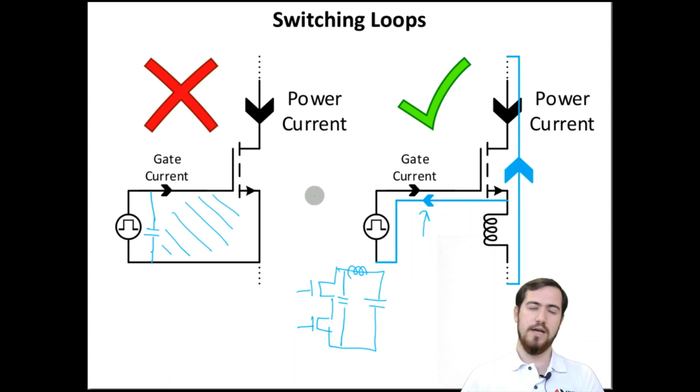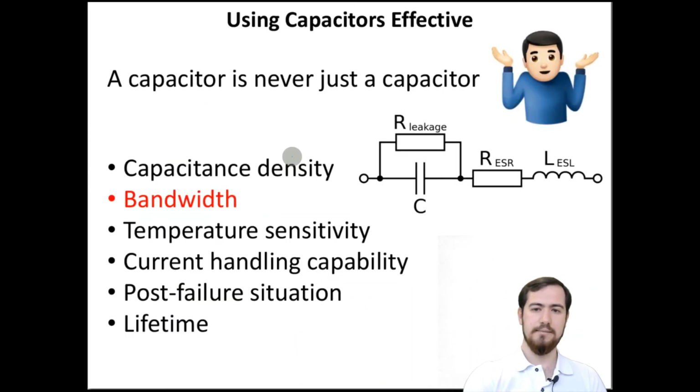So in order to increase the tolerance of our layout for DC and AC currents, most of the time we use power planes, which are the copper regions laid on our printed circuit board. These are the important tricks to minimize the resistances and the inductances for our critical layout design.